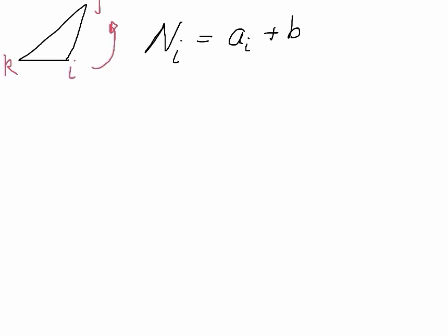We defined our triangle. We labeled it I, J, K, using a counterclockwise direction for our labeling. We said that our basis function, because it's linear, was going to be at its very simplest a sub i plus b sub i x plus c sub i y.